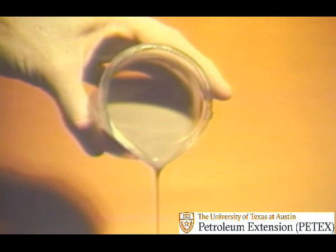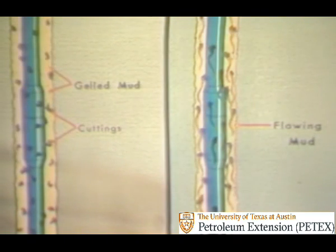In addition, gel strength is obtained. That is, as at left, when the mud is not flowing, such as when a connection is being made, it temporarily solidifies or gels and keeps large cuttings from falling. But as at right, when the mud is pumped, it thins and is able to flow.